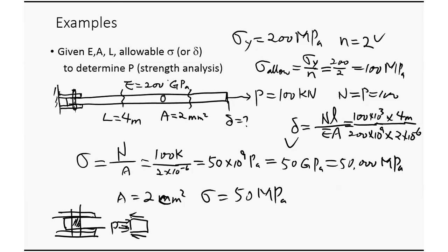So how much is this force here? It's load P. It's how much you're pulling from the bar, 100, right? For the boat, it's stuck between the 3 things. So you're pulling 100. So this part is 100 pulling. Now how much is this shear? What's the shear force? 50 each, one on top. You can write the equation of equilibrium, so V will equal 50.